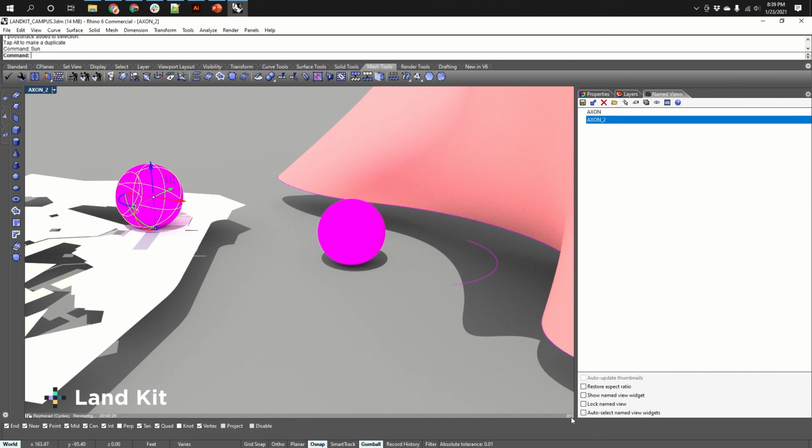But this takes some time, and you can see the number of steps it's going through. After a while, you get an intuitive sense that a 500 step render takes a minute with relatively simple conditions. But if I had really complex stuff, that would take 10 minutes or something. So the neat thing here is that you can make renders essentially right in Rhino, and you can type view capture to file.